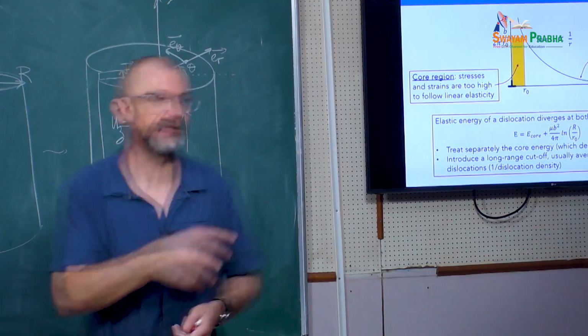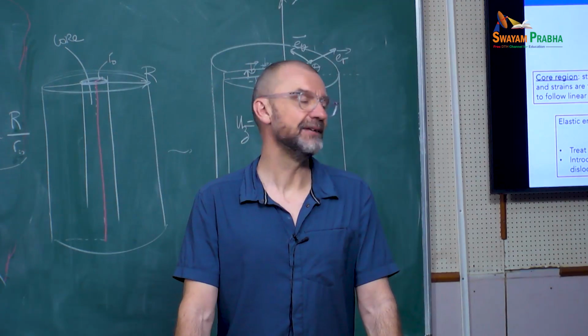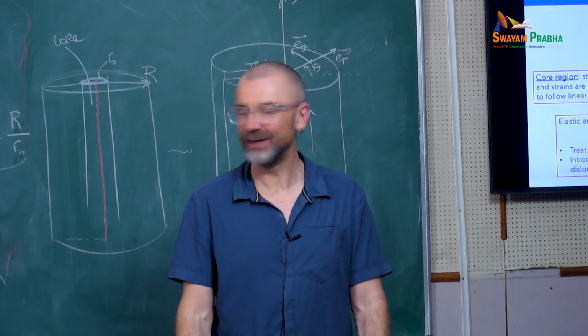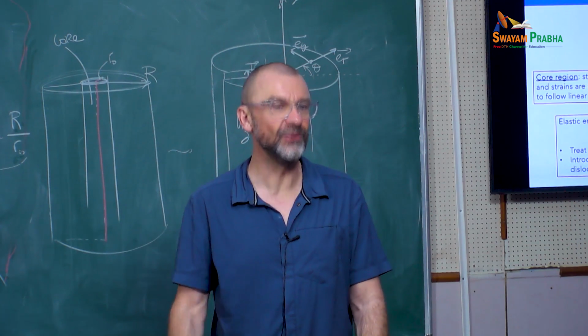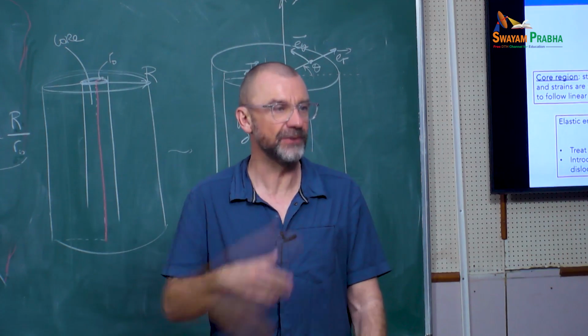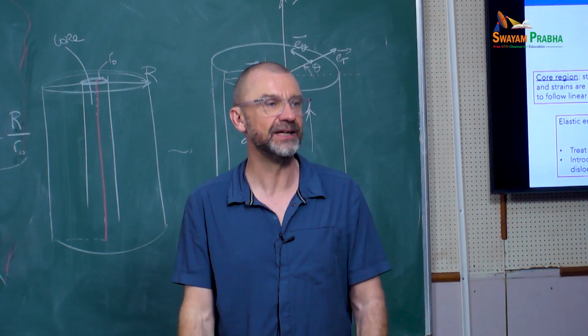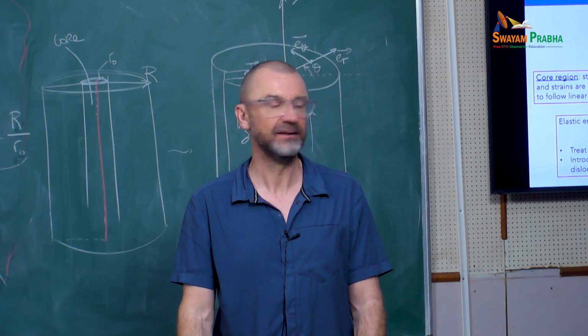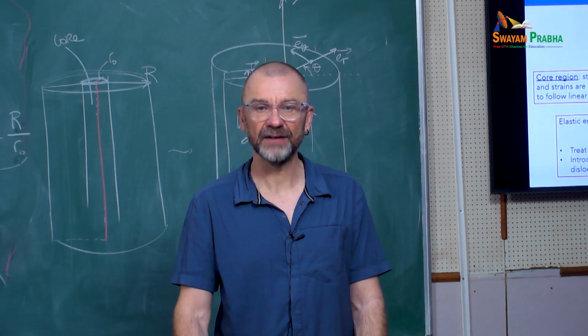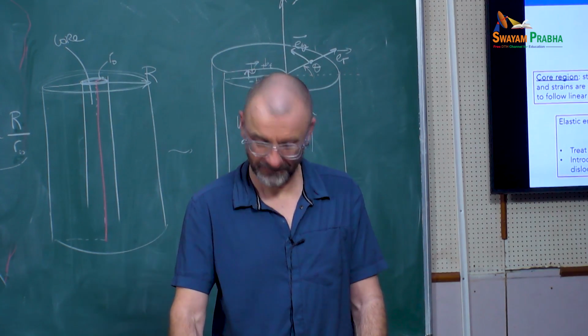You'll see examples this afternoon in FCC crystals. Yeah, even with nonlinear elasticity you can gain a little bit, but there's still a point where it breaks down. You really have to put in the atomistic nature of the material, like with a Peierls-Nabarro model, to get something that makes sense. Yeah, nonlinear elasticity doesn't work. It's fine for the others. Yes. Okay.